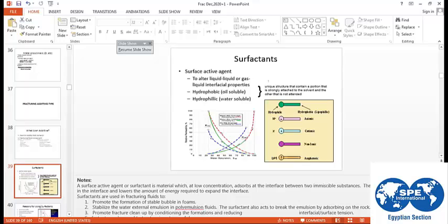However, you should be careful with this, because it could be affected by a change of the rate. Because of this, I said in the beginning that we should guarantee the rate is constant in this period. So if you want to measure the fracture gradient from the data frac, it is better to start with a low rate at the beginning until you get the fracturing point, then calculate the fracture gradient. After you say that this is our frac point, you can start to increase the rate to make the data frac.